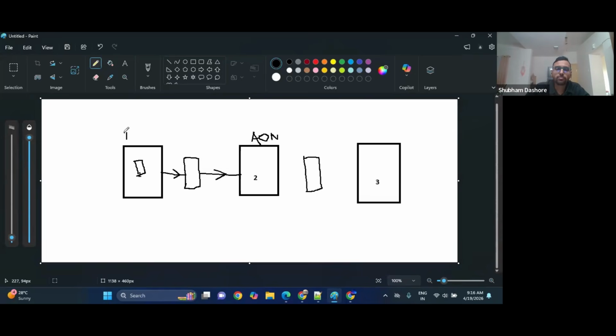Whenever everything is turned off in the gated domain, some critical signals need to retain their previous value. How can we do that? With the help of a retention cell. Whenever the domain is turned off, those critical signals retain their previous value through the retention cell, and retention cells have a different supply, that is only the retention supply.